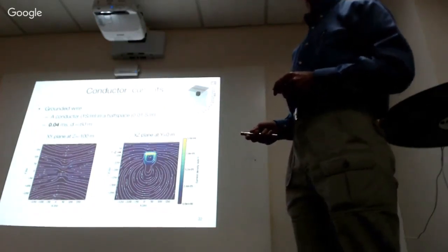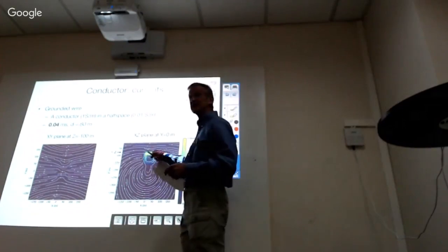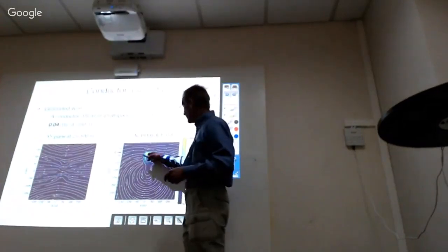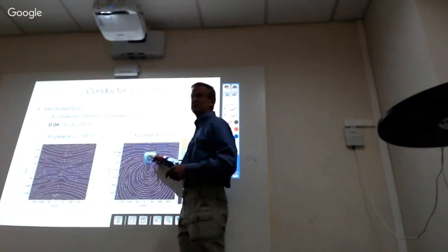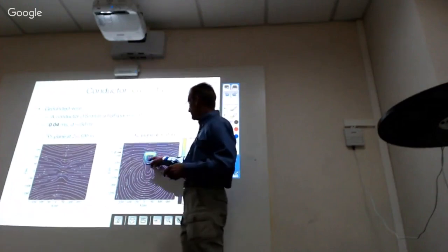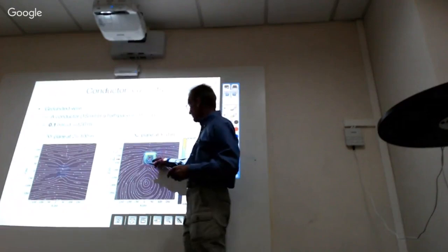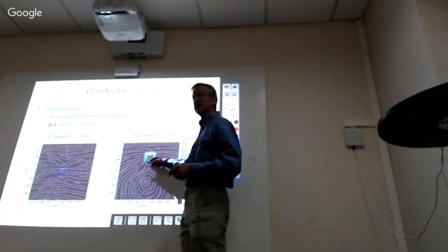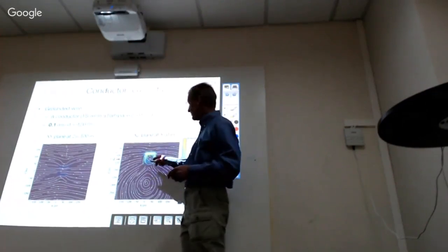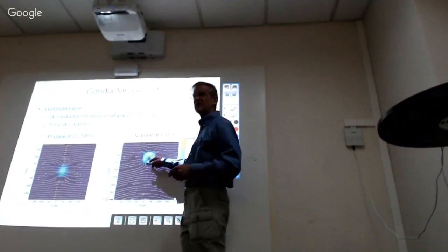Those are the currents. They're doing kind of what you think. First of all, they're maximum towards the top, okay, because the energy is still diffusing now. But look at the shape. Those are circular currents. So those are the vortex currents that we're thinking about, right? Now what happens with time? As time goes on, these currents diffuse inwards. There's still vortex currents that are there. Later, they become more uniform, and then they're gradually dying out.